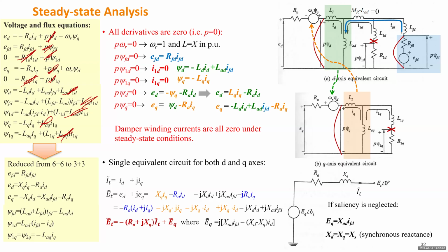This EQ is just the magnitude of some phasor value, like a voltage waveform. That waveform is proportional to the magnitude of the field current. So your question is, partially related to XD, the D-axis reactance.